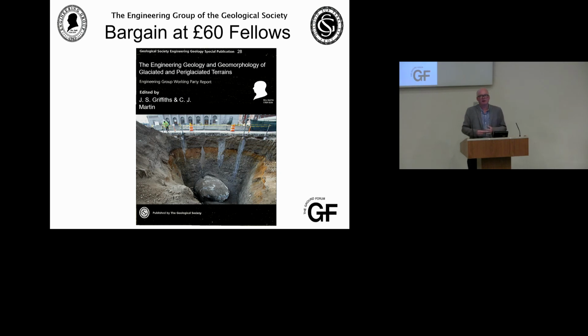And so we looked at loess as a material. We started to understand the difference between loess and brick earth, as a significant periglacial deposit. So part of that key chapter was to break down the wind-blown sands: loess as a primary material, brick earth as perhaps a reworked loess, and what have you. So that's what we tried to differentiate. What are the materials that you would expect to find in these environments, and then their significance. So yes, it's still thought of as a primary loess down in Pegwell Bay. And that, of course, was significant for High Speed 1, the Channel Tunnel Rail Link, and then starting to potentially recognise that elsewhere as an infill.